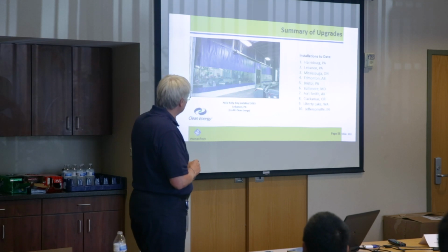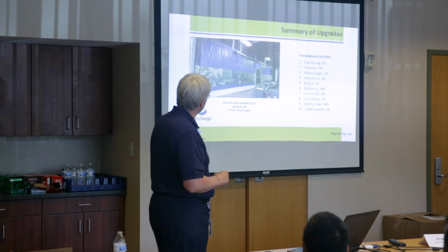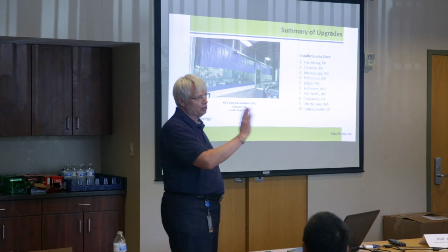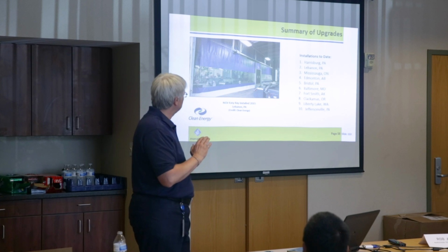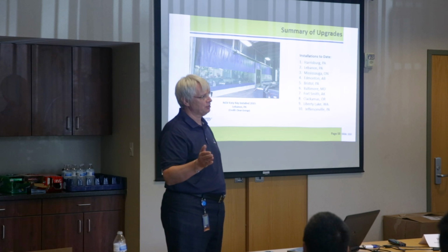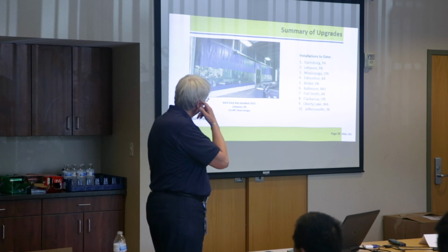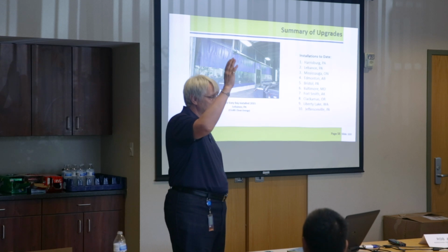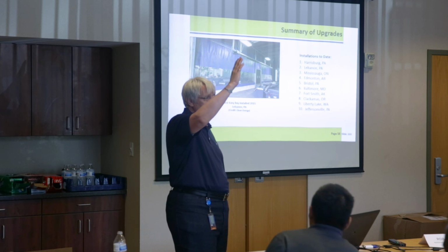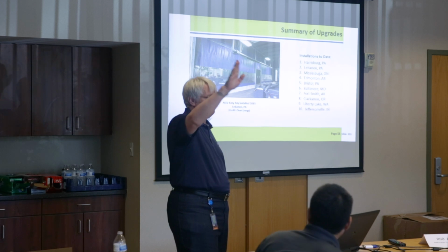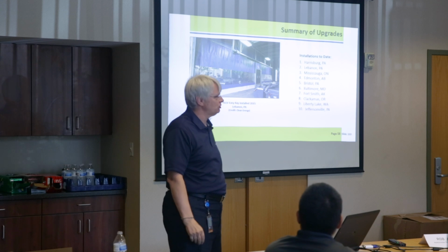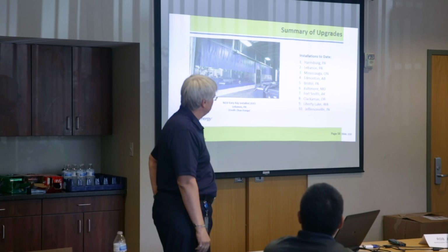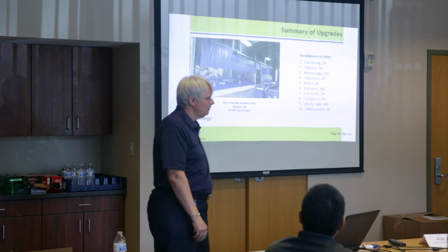But you can see here that within this space, these are just really curtain walls. And so there's no fire rating in the wall. It's just controlling the migration of the gas release. And it would be up near the ceiling space. It would have to essentially seal off that particular temporary room, I guess, from the rest of the garage. And it would have to have its own HVAC system.